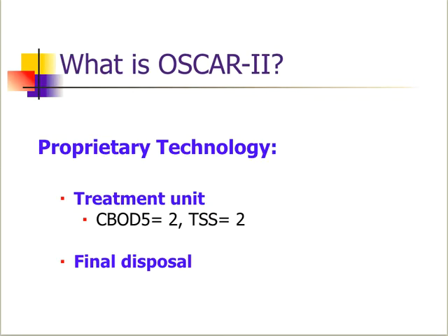The Oscar is a proprietary treatment technology. It does produce a high quality of effluent from septic tank effluent to a BOD of 2 and a total suspended solids of 2 milligrams per liter, and it also acts as a final dispersal component at the same time.